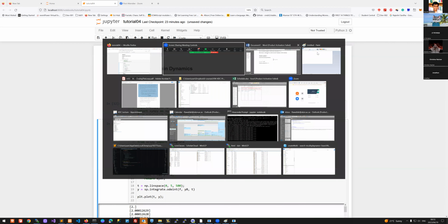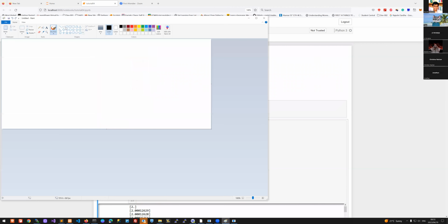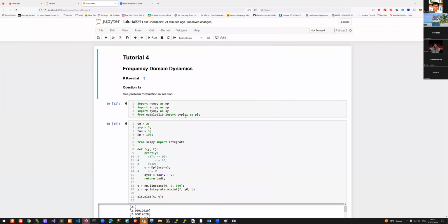We said, if you have an ODE and you want to integrate it, then you would basically take an initial condition, like in our case, we are starting with a 2 here. Then you stick that value of 2 into your ODE. So we know initially our y value is 2. We know our set point is 3. So on balance, this is a 1. And that defines a value for u. And then this is 2, the initial value is 2. Tau is 5, so that's a 10.